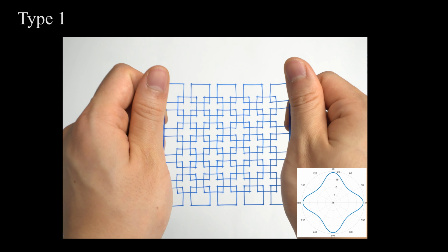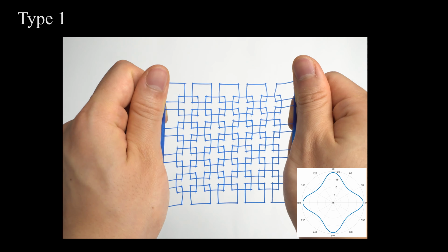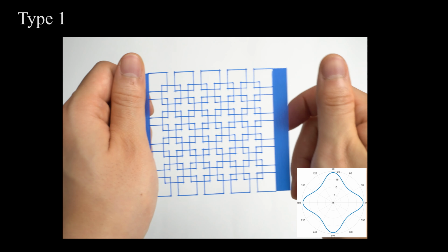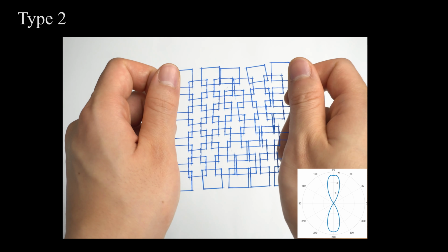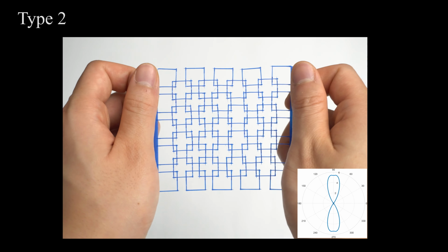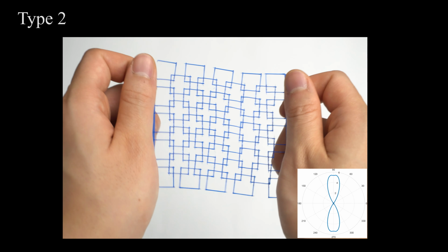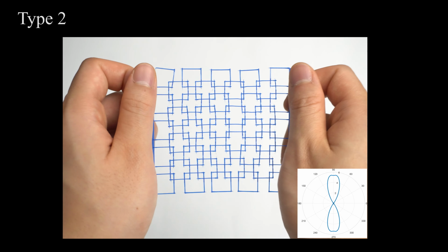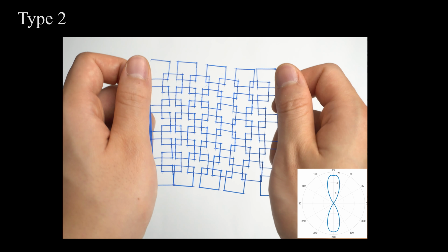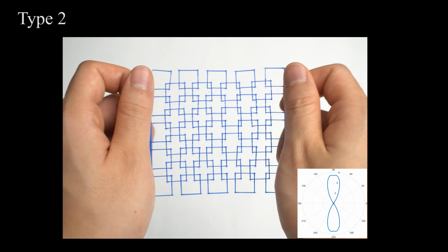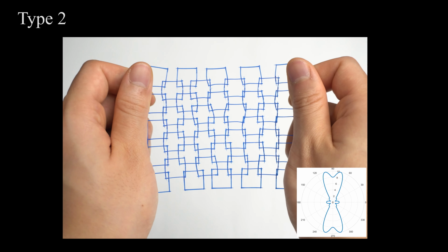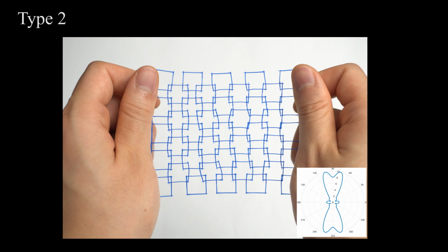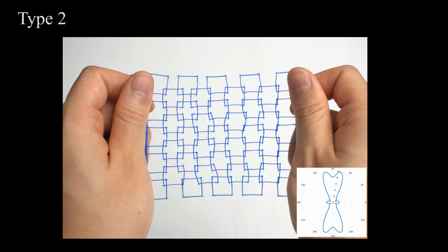To analyze the direction-dependent behavior of the structure, we show a corresponding directional stiffness plot obtained using data-driven homogenization. When substituting all fused connections with channels that allow only horizontal motion, we observe a significant change in the directional stiffness plot with 0 stiffness in the horizontal direction, an effect that is explained by the structure absorbing all of the imposed deformation through internal sliding. However, as we increase the magnitude of the imposed horizontal deformation, all squares eventually reach their sliding limits, and the material exhibits finite stiffness from there on.